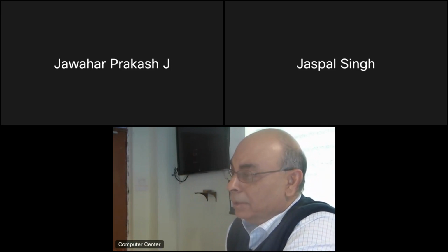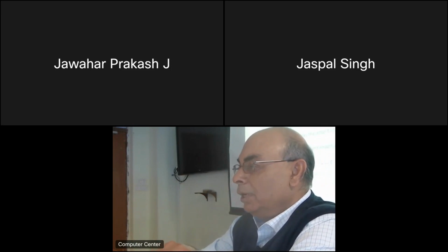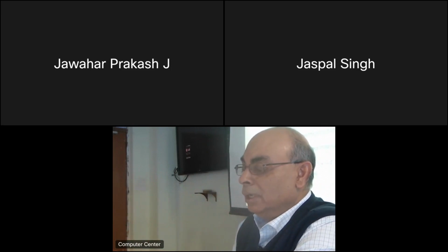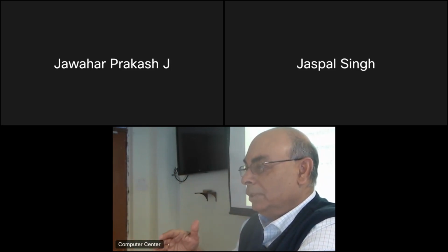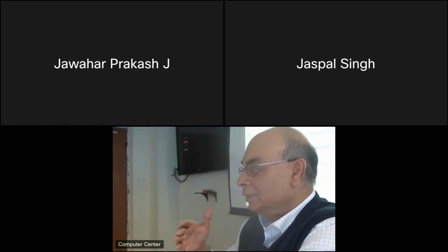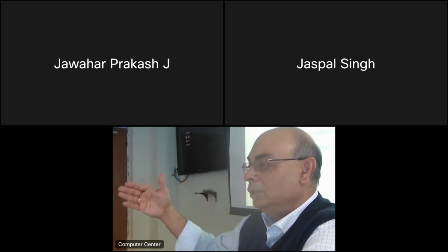The only thing I did here, and this is something to just be careful about: see this phi, which I have written with a tilde on the top. This phi includes the propagational phase and other phases, because this is a phasor, right? There's a relationship between a phasor and the envelope. The phasor is the envelope times e to the minus jkz, because jkz is just the phase shift because of propagation from one plane to another.